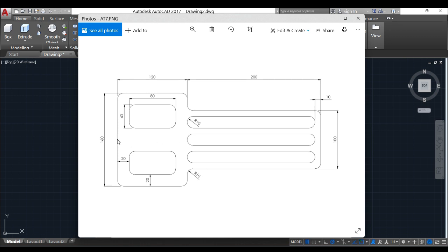So we will draw a center line here. So let's just continue. Draw a center line here, make it up by 50, down by 50 to get this line and this line. Then we will offset this by, this is already 120 and this is 200, by 320. Or we could simply draw a line here and offset by 200.